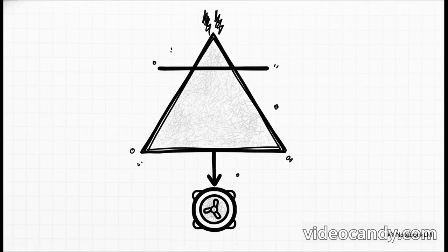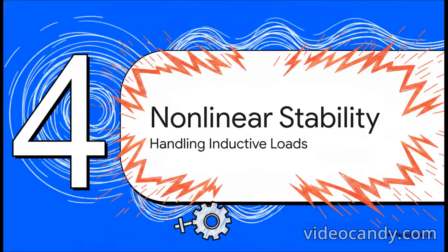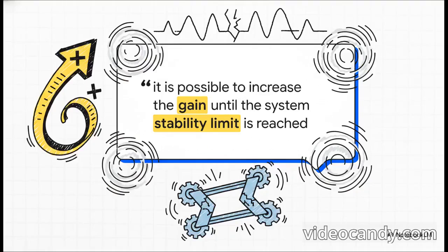By snapping the ADC sample point directly to the center peak of the triangular wave, all that nasty high-frequency switching ripple noise, which is localized on the voltage transitions, naturally cancels itself out. You filter out the noise without ever having to introduce a software low-pass filter, which would inevitably add processing delay. Plus, this precise duty cycle adjustment gives us incredibly high-resolution command over the power stage, carving out a flawless, zero-lag execution pathway straight from the DSP down into the motor coils.